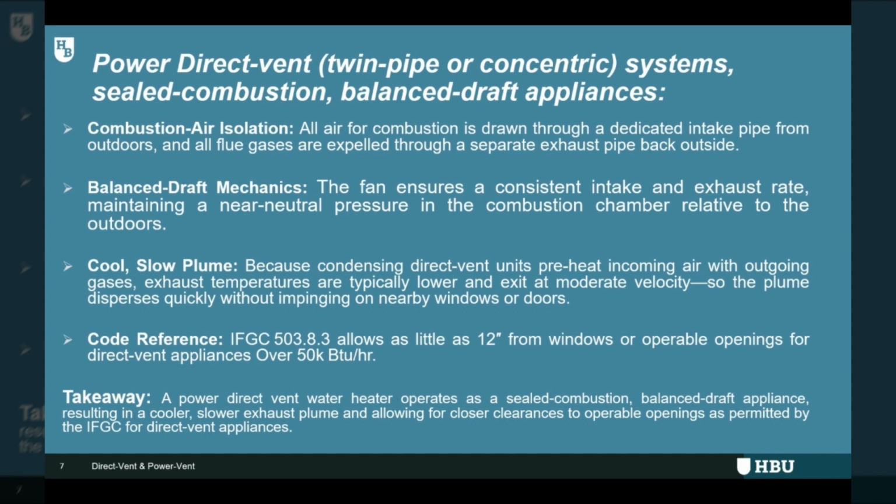And finally, the code reference. The International Fuel Gas Code, specifically section 503.8.3, recognizes these safety features and allows for vent terminals of direct vent appliances with an input over 50,000 BTUs per hour to be as close as just 12 inches from windows and other openable openings.